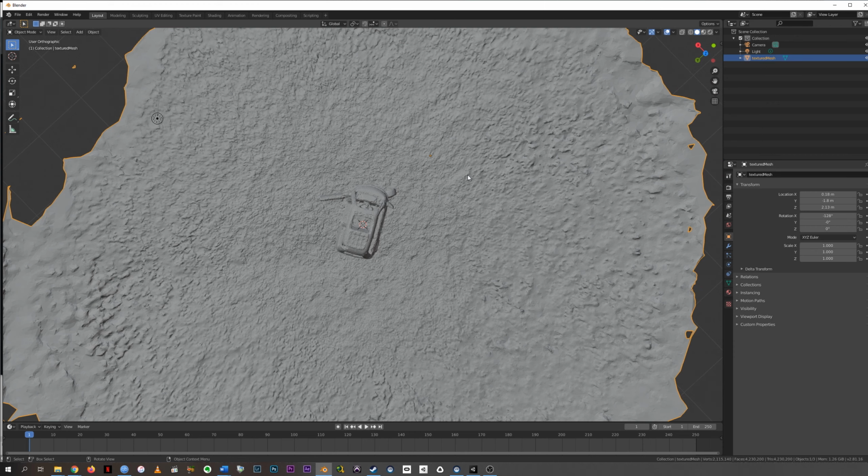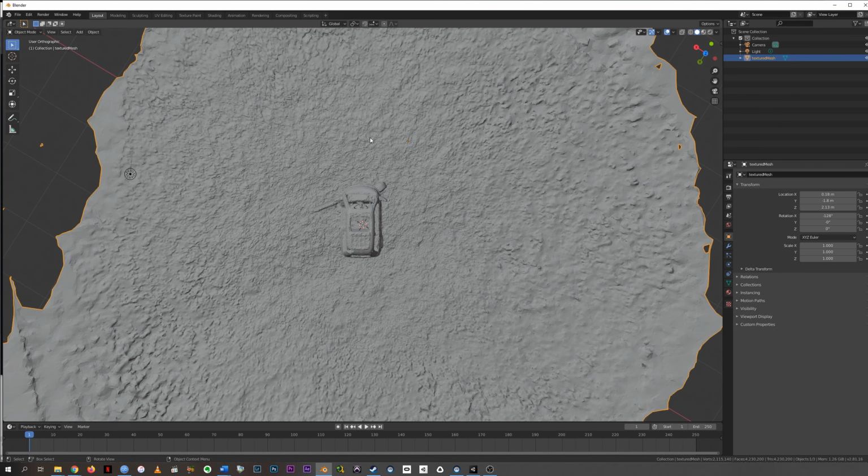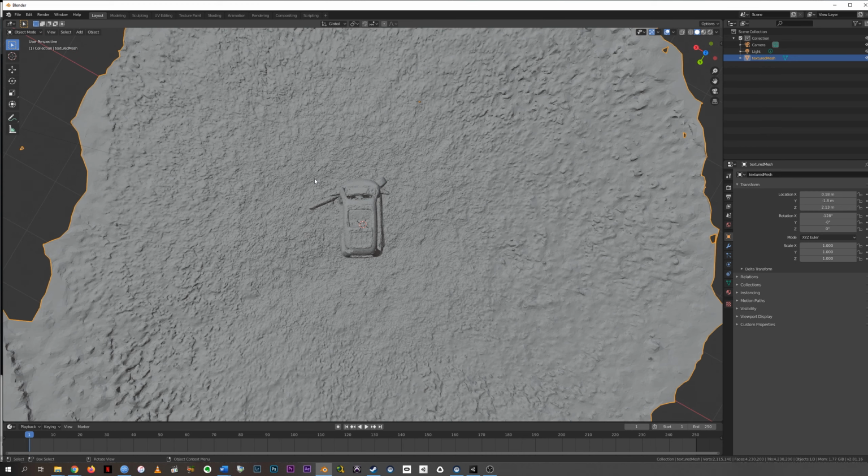And here's how. On the keyboard, I'm going to hit 5, which is going to make this view kind of flattened in like an orthographic projection. And then I'm going to hit 4, which is going to sort of lock my camera to bird's eye. And now I'm doing that on a keypad on the side. Just the regular 5 and 4 do not do that. Okay, so now I'm going to hit Tab on my keyboard. This is going to bring me into edit mode.